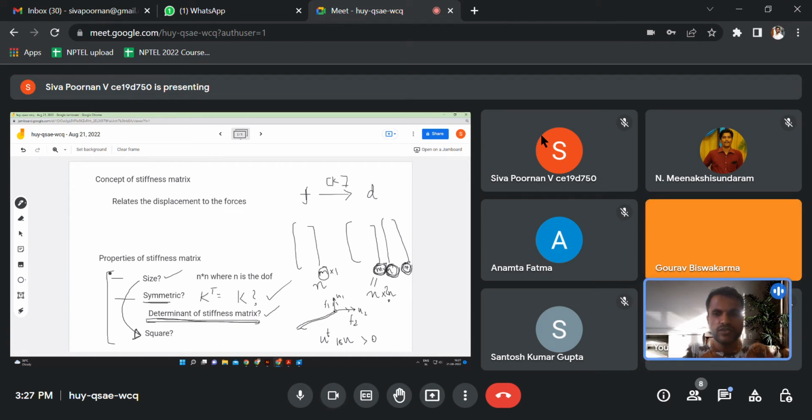Yes. So there are two things that I want to point out. But by the way, this is a very good question, and no question is stupid, right? One thing that I want to point out is that boundary conditions we always put on displacements. Forces, as far as I know, we fill up with known forces. Yes, because boundary condition itself means that we are having some conditions on the boundary in terms of displacement. If we have forces, then probably we will allow displacement at that point, and that is not coming in the boundary condition.